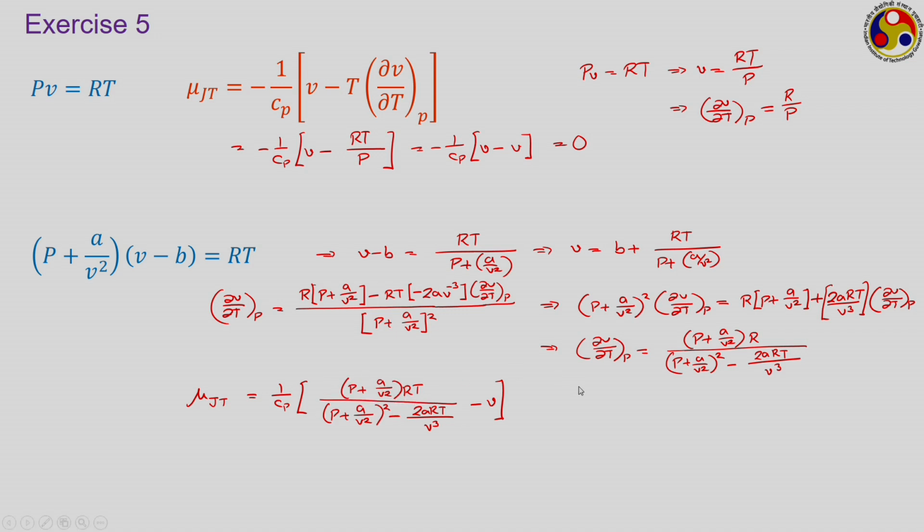Let us quickly move on to discuss the final concept in this particular module, which is of the Clapeyron equation. Clapeyron equation is the application of the Maxwell's relation during a phase change process. It can be any kind of phase change process, liquid to vapor, solid to liquid, or solid to vapor, or vice versa, but the Clapeyron relation provides us a generalized platform of calculating the changes in entropy and changes in enthalpy during a phase change process.